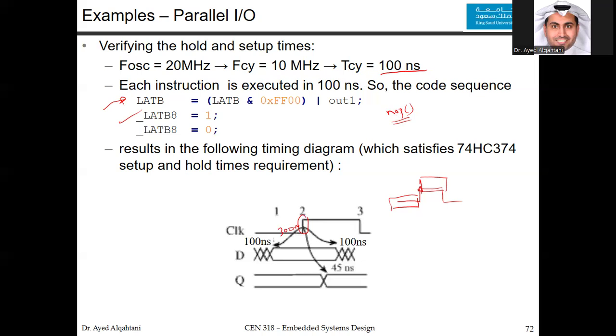This time we talked about the GPIO, port A, port B, how to configure their TRIS, the latch value, or the LAT, and the port value. We looked at the pin diagram, and we talked a little bit about the Schmitt trigger buffer, and how the latch value and the port value differ.